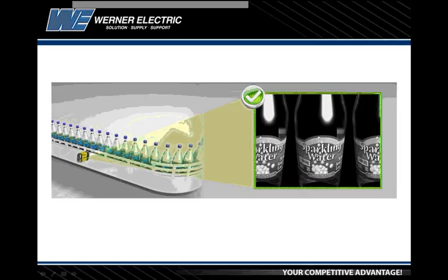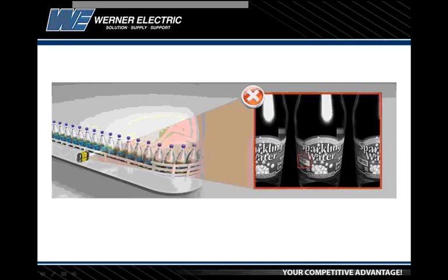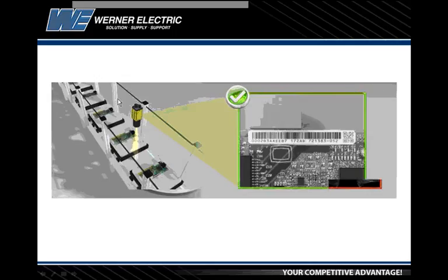And in this case, on the left side, there's a Cognex DataMan 300, which is a barcode reading specific camera. It's capable of reading barcodes at a very high rate, and that's all it does. So if the barcode is damaged or it's the wrong barcode because somebody loaded the wrong set of labels on the labeling machine, then there'll be a fail signal for that, and the operator can check and see if it was a one-time thing, the product can be kicked off, or if it was a mistake in loading the labeling, that can be corrected as well.